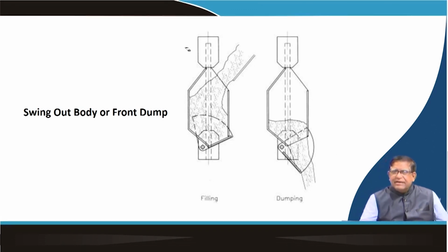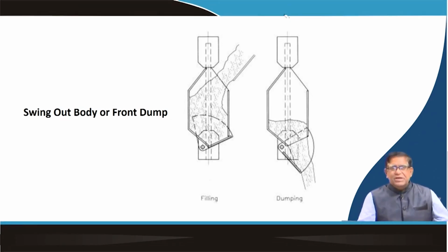It comes out from here, this is the spout through which the material will be going like this. So, a mass flow will have to take place. We need to see that inside this surface, sometimes if the material is sticky, you may have to keep a liner so that the material flows well, as we have seen in the bin and bunker discussions. So, the skip is the device which goes up and down the shafts, and it is loaded there.